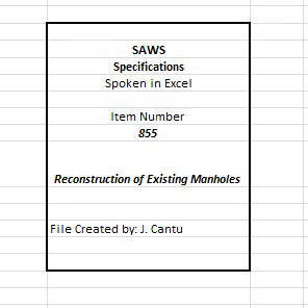C. The owner may elect to simply remove and replace the existing manhole with a new one. D. Any manhole excavated for repairs or excavated for tie-in, shall be backfilled to 1 foot above the top of the cone section to allow for the concrete ring encasement. E. The contractor also has the option of backfilling with approved secondary materials, subject to the provisions of specification item number 804, excavation, trenching and backfill.